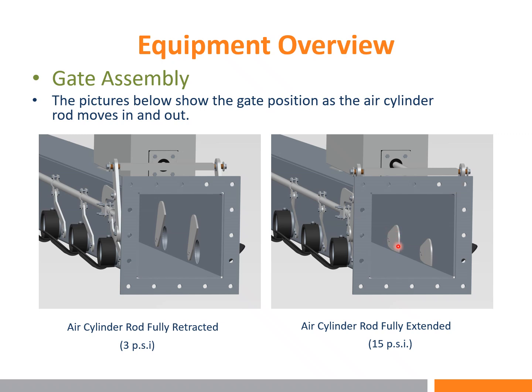But just be aware that the linkages cause these gates to open and close opposite of each other. As these are opening, these are closing, and vice versa. So in this scenario, it would allow counter thrust out the side of the arm to slow it down. In this example, they would be closed, so you're getting thrust fully from this side of the arm to speed the distributor up.